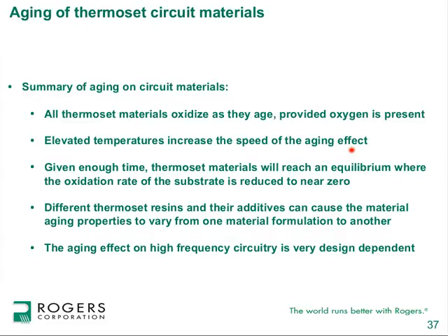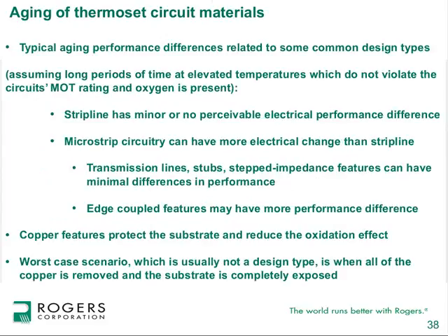There are a lot of different thermoset systems out there, different thermoset resins with different additives. Really what that means is not all thermoset materials behave the same. Different formulations can age differently than other formulations. And the bottom line is, from many, many studies we've done, and I'm willing to share, we find that the aging effect is very much design dependent. So it's very much dependent on the circuit design itself.